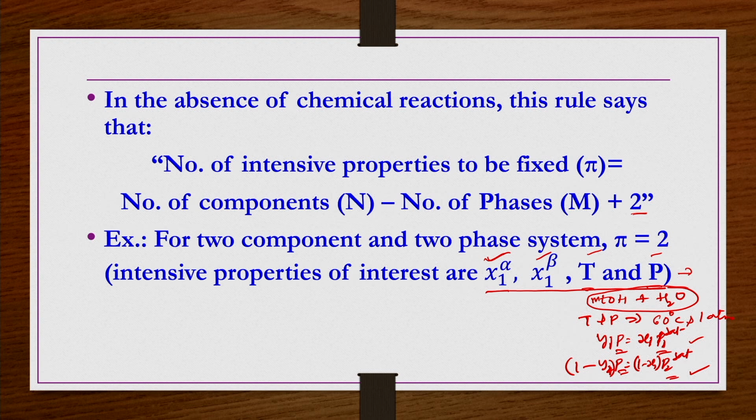That is the point of this phase equilibrium problem. Even if you have some non-ideality in these phases, then we have this pi 1 and gamma 1, this pi 2, gamma 2. So, these we can calculate; we can obtain this pi 1, pi 2, gamma 1, gamma 2 describing the non-ideality of vapor and liquid phases, and then we can substitute here and again find out y1 and x1. Okay.